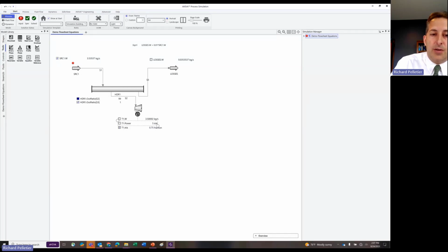And if there's a flow requirement coming off of here, in order to maintain this balance, I need to then bump or change this flow rate here going into the header, right? So it knows that these things are all connected, and it can tell you what you need to do in order to rebalance the file.